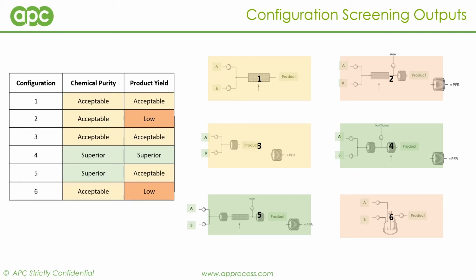not. On the current slide, we can see a ranking system for each of the individual configurations screened for an alkylation reaction. And we can see which configurations give acceptable purity and acceptable yield, but it will often be very clear, as in this case, which configurations give a superior yield or purity. In the above case, it can be seen that a dual PFR system is favourable with an inline quench of the reaction intermediate with either a packed bed or a pre-dissolved quench. And this was tracked by an in situ FTIR probe and verified using HPLC data.